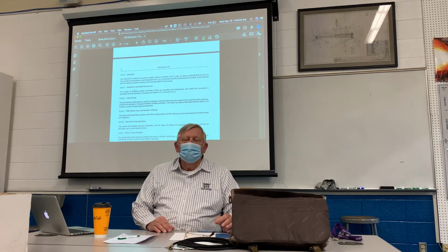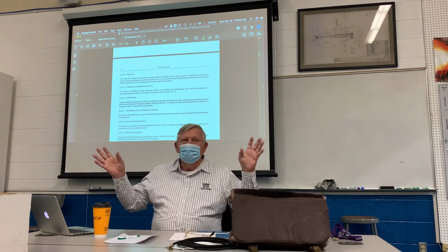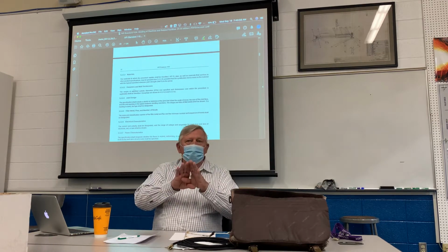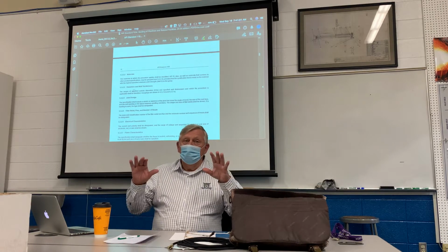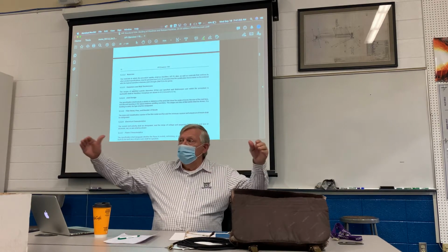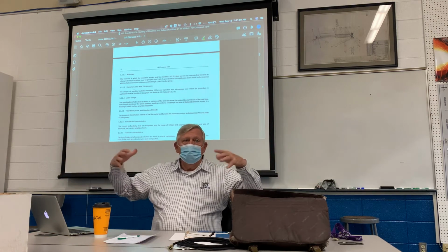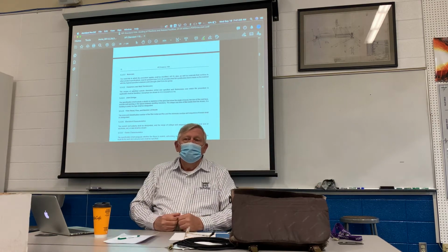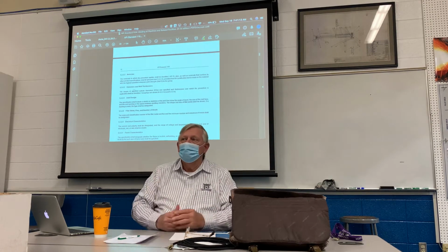Because if you wanted to weld 5 chrome to 314 stainless, just be crazy, and you're going to write a welding procedure for that. Just knock yourselves out. But the more exotic you get, the more you're going to have to research beyond the document. So be easy on yourselves. We're limited to API, so that's a smaller grouping of everything.